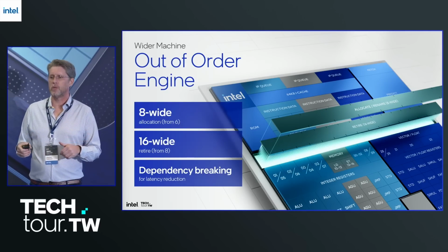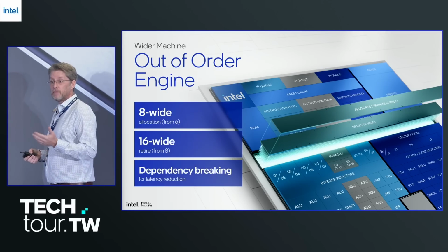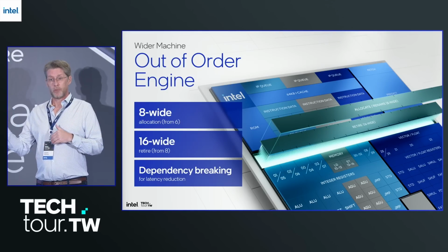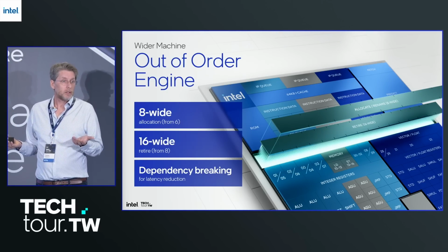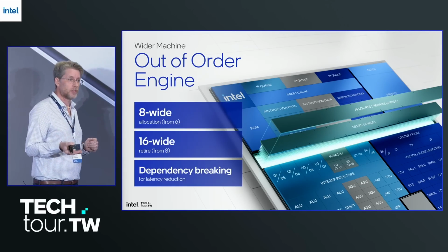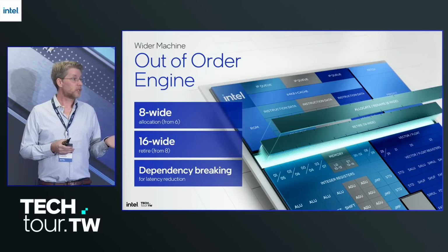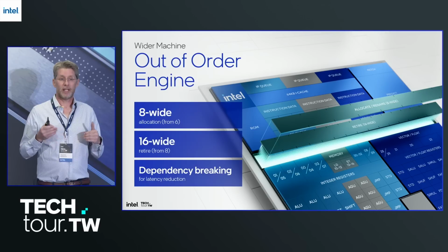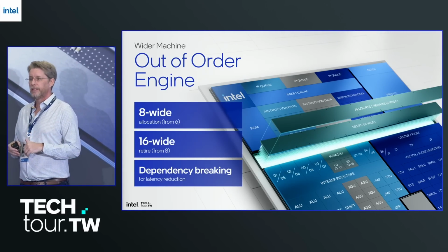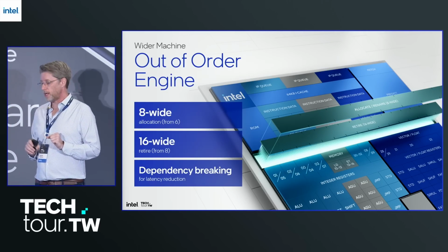You have an instruction that you know will produce a zero. So that's one example of breaking a dependency. We have more. We have cases where we will take a load that we predict is going to forward from a store, and here we know of that connection, so we don't actually feed the load data to the dependent UOP. We can feed the previous store data. Another example, in x86, we have been doing ESP folding, where we take the stack pointer and we kind of accumulate the offset. We can do that in more cases now as well. So that's the dependency breaking.